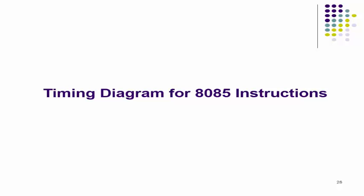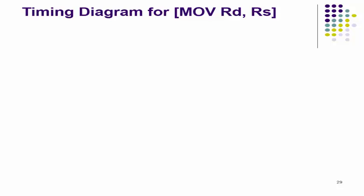Hello friends, after the discussion of various machine cycles of 8085 microprocessor, we will move towards the timing diagrams for the various instructions of 8085 microprocessor. So the first instruction is MOV Rd, Rs, a simple data copy instruction. Here Rd is the destination register and Rs is the source register.